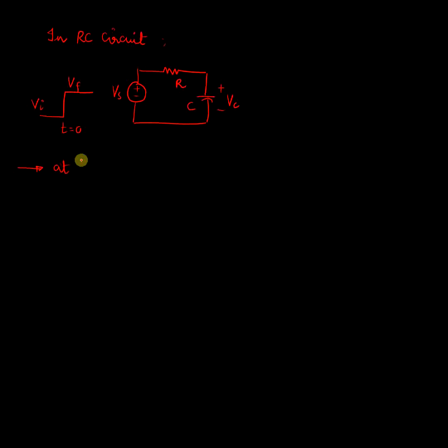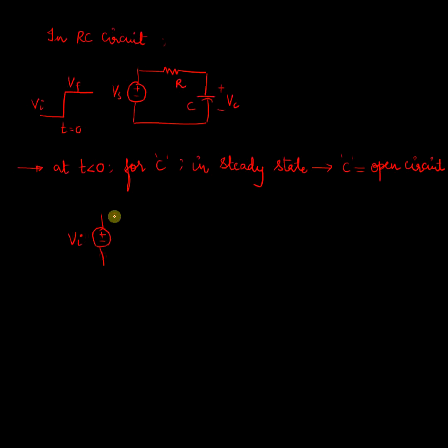At time t less than 0, as we know, for a capacitor in steady state, the element acts like an open circuit. So I can consider the equivalent circuit for this, wherein I have the input voltage Vi, a resistance R, and here the circuit is open.